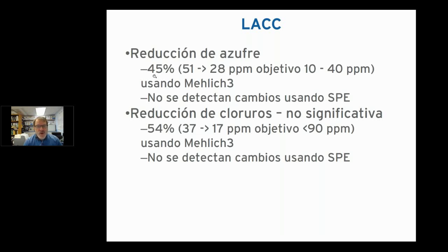I think what it means to me is that in the cases of looking at salinity issues, when the salt levels are not that high, as in the case of Los Angeles Country Club, Mehlich 3 extraction is going to work well, and you don't need to use saturated paste extraction. That was just one test. We wanted to compare those two analytical practices because we use primarily Mehlich 3 extraction on soils, and it seems like it's okay, and that saturated paste did not provide additional information.